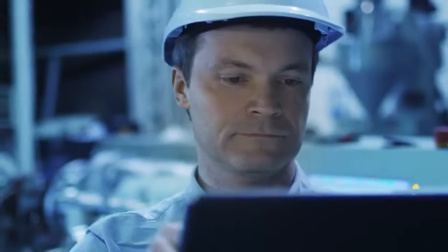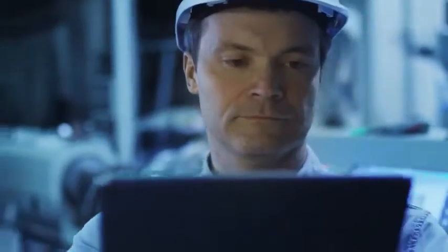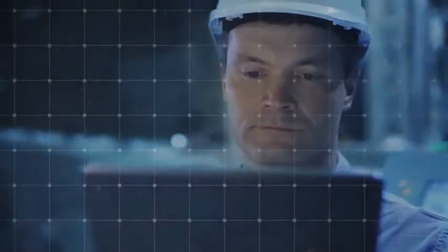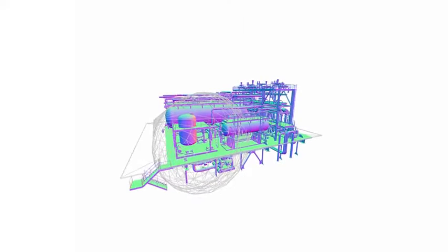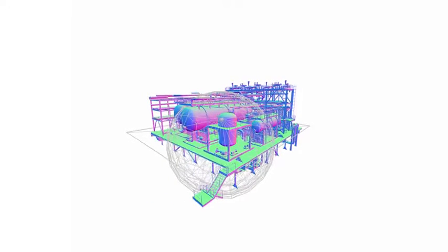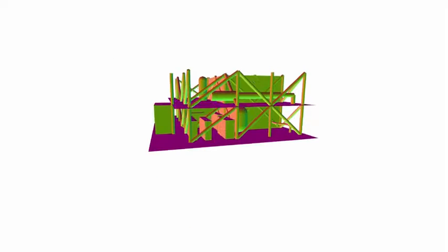This has now changed. It is now possible to design consistent and effective fire and gas systems utilizing a technique called fire and gas mapping. Fire and gas mapping provides a framework for evaluating the effectiveness of a detection system based in mathematics rather than judgment. The process begins with defining the facility that is being analyzed.